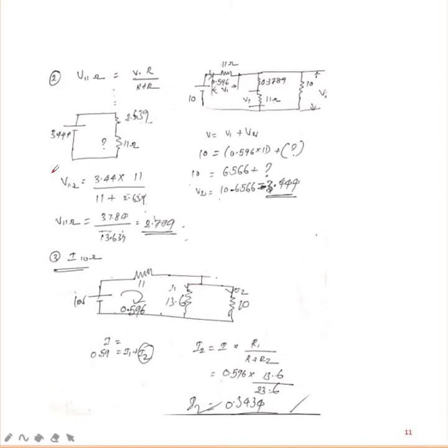Then the voltage division rule, you are going to find out very carefully. Here is a 10 volt source. 10 volts is V. This is the V1 terminal and this is the V2 terminal. See that, V1 terminal, V2 terminal. Be careful because it's a series circuit. This is one part and this is another part. So the voltage will be divided: V is equal to V1 plus V2 only.